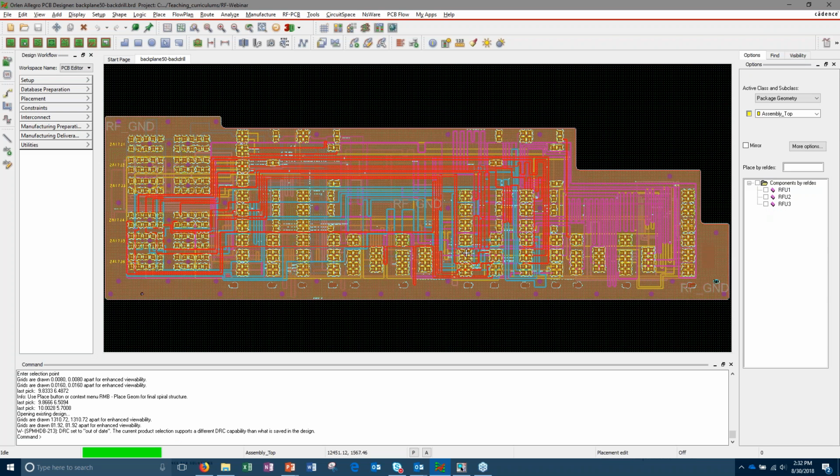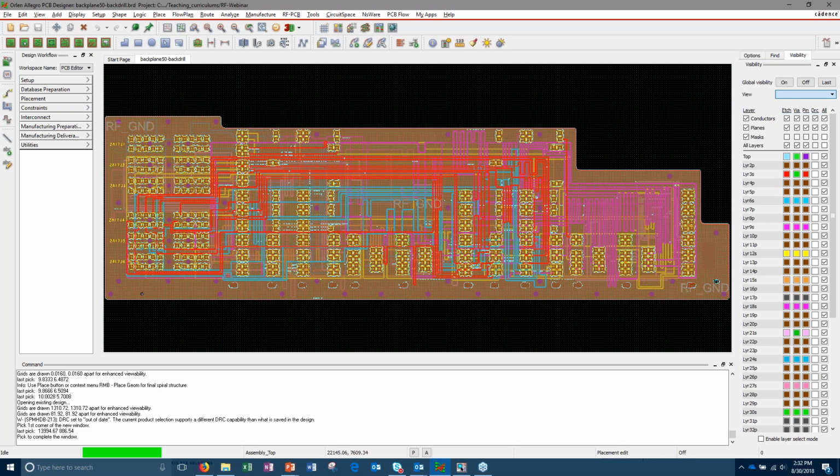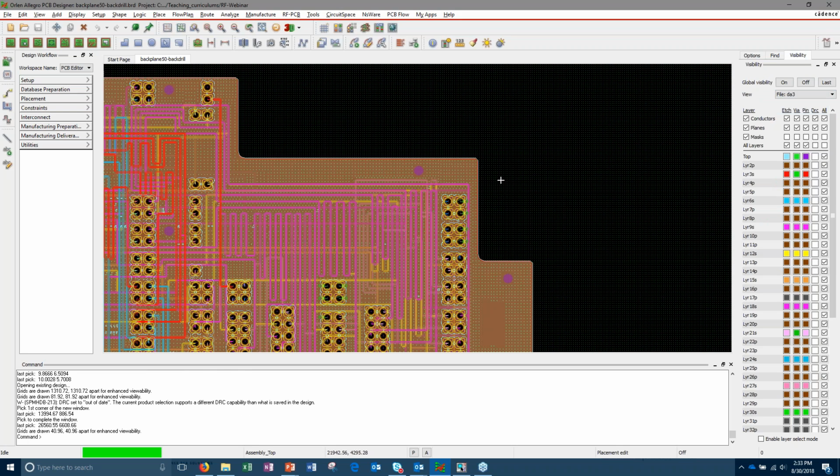There we go. Let's see if my visibility works for this one. Yes, it did. Fine. So this is that high-speed backplane, and since it was running at such speeds, everything had to match. As you can see, all these RF traces are in here, and they're tuned and matching in the actual length, flight times that you need in there. But I wanted to talk about back drilling.